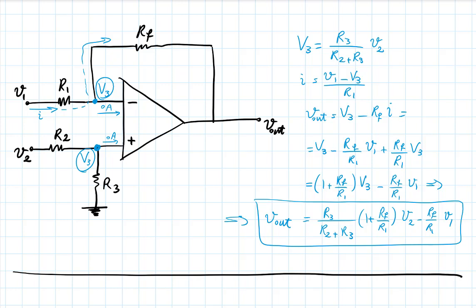Now, I have a question here for you guys. I have solved this circuit without having connected anything to the output, right? Now, maybe I was just interested in that output voltage. Maybe I was just going to connect a voltmeter there. And a voltmeter does not draw any current, so an ideal voltmeter is as if it's not there. No problem. It's like this.